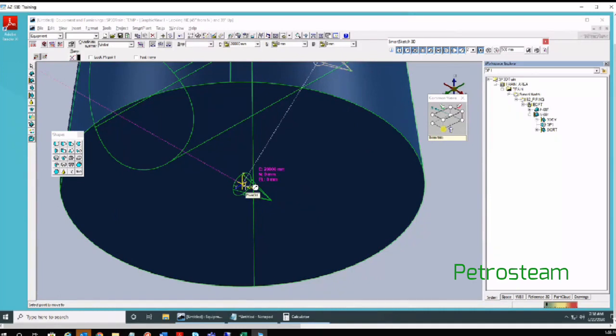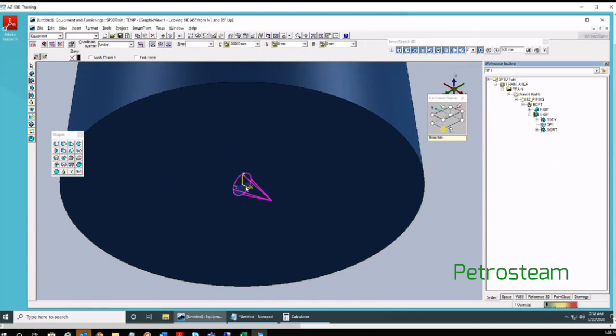Okay, now the key point is visible. You can see this is your key point shape, and to confirm it, at the top pinpoint bar you can see easting is 20 meter, northing is 0, and elevation is 0. That is what your required point is, except this point. And you have moved your DP point to that location.